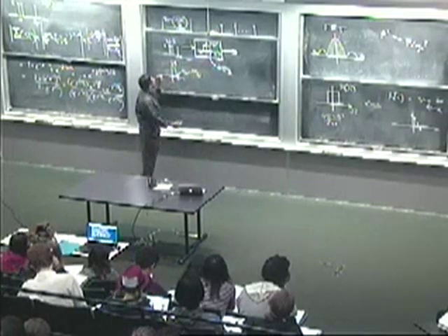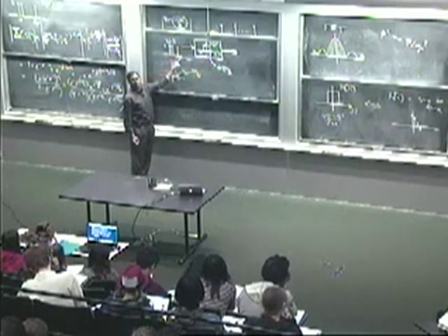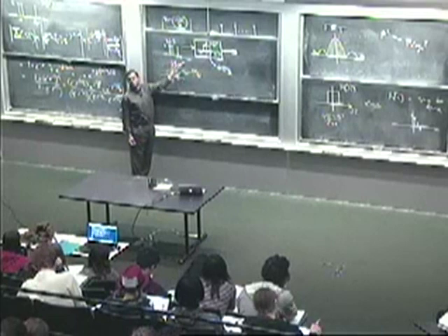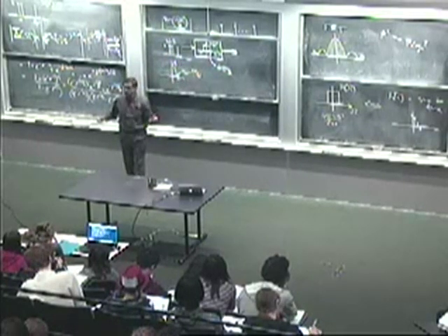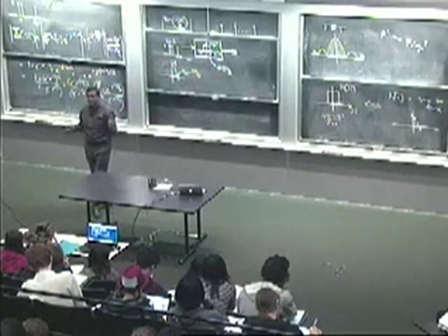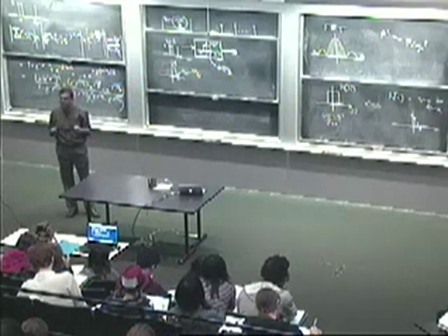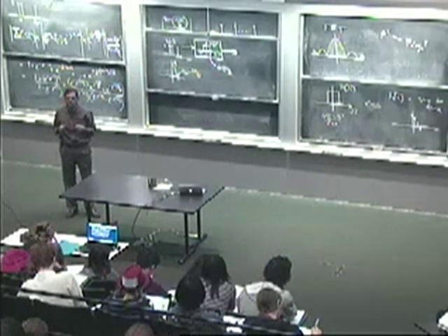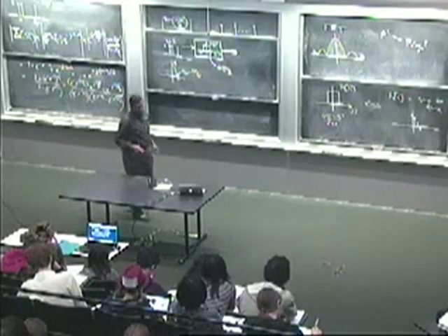So you see, what I'm trying to do is not have the sharp discontinuities, the 0 to 1 and the 1 to 0. I want a more rounded behavior in the time domain, so I get a sharper concentration in the frequency domain. And you can actually see how that works.